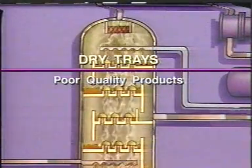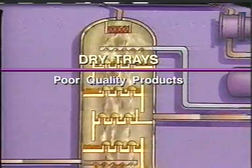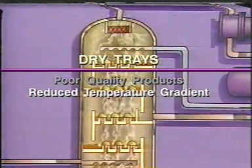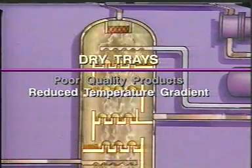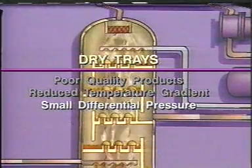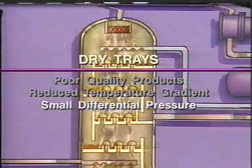First, the tower will produce poor quality products because no fractionation can occur on a tray without liquid. Second, the temperature on a series of trays without liquid will be about the same, so the temperature gradient in this section of the tower is very reduced. And third, there will be a small differential pressure through a series of dry trays because there is no liquid to resist the flow of vapors.